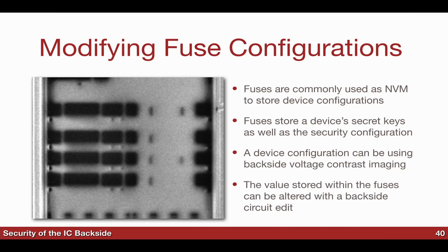So the interesting thing that we thought of next was something covered pretty well in the console hacking talk yesterday, which was how you do crypto in modern days. A lot of times they use one-time programmable fuses to program a key into the SoC. What we see here is an area on an ATmega microcontroller, because then we could easily play around with the fuses and set them and clear them.